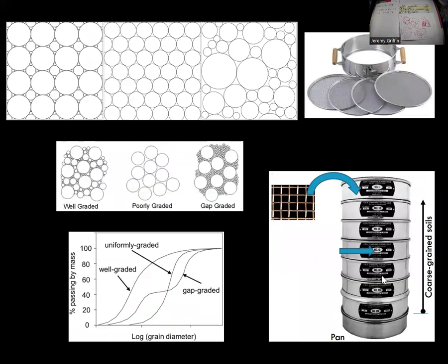This sieve, you guys see the sieve right here? The sieve has these different sieve layers that have different wire meshes with different size holes in them. So if you have some soil sample and you dump it in the top, you see how it's going to separate out the sizes, right? Only the large stuff is in the top, and then everything else goes down. And then only the finest particles, like your dust and clay particles, can make it all the way to the bottom, right? Through this very fine mesh.